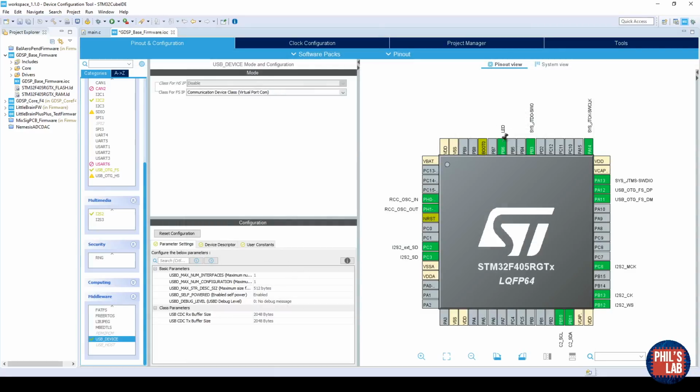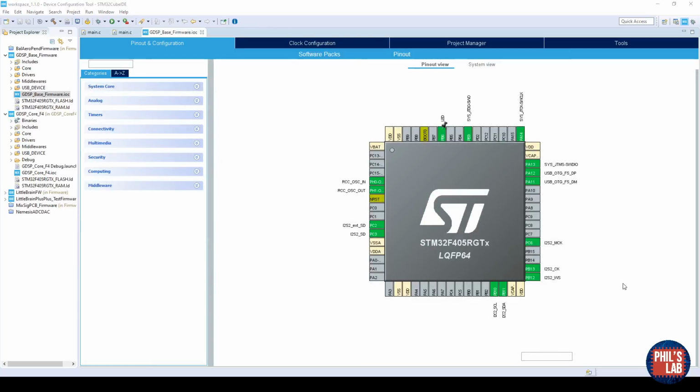Now we can move on to actually going deeper into this basic setup that includes setting up DMA streams and so forth. Because we just want to do very basic setup with our I2C connected to our codec, I won't be using DMA for that. Initially, our codec will just be set up at the start before we go into our main while loop, before we do our main callbacks, so we don't really need to use it that much, especially not for very high bandwidth transfers. So for I2C, we can just leave everything as it is.